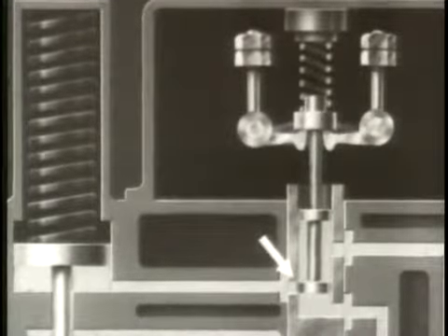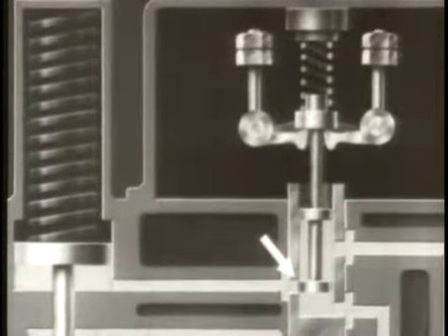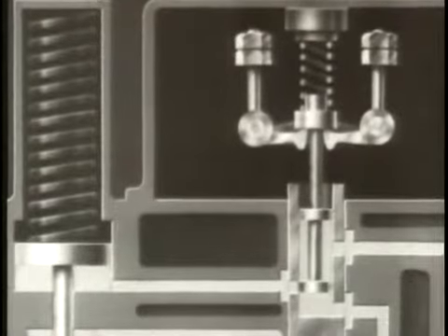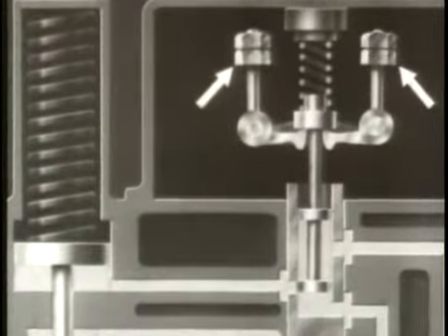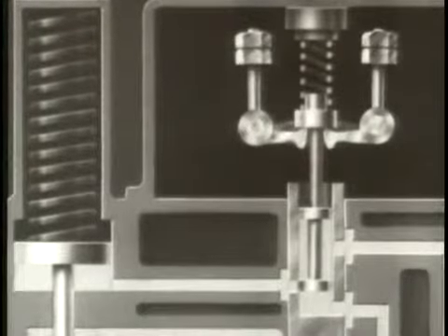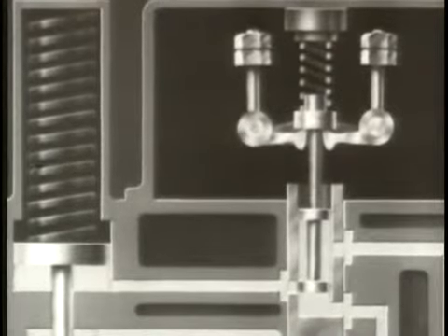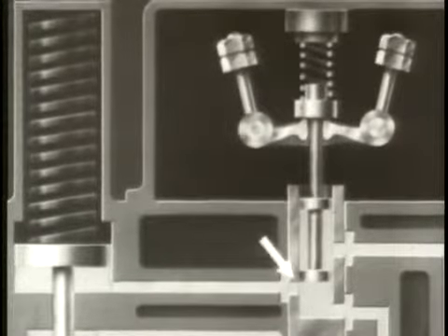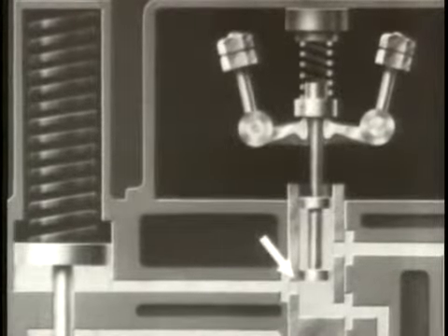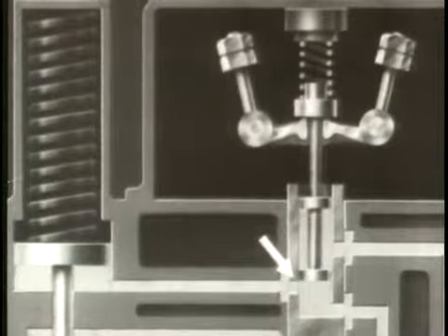When the engine is running at a set speed, the port to the power cylinder is covered by the pilot valve plunger. The plunger is held in this position by the flyweights. If the engine load decreases, however, the engine speeds up, and the additional centrifugal force throws the flyweights outward, raising the pilot valve plunger. This opens the port,